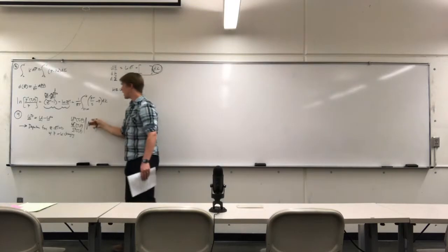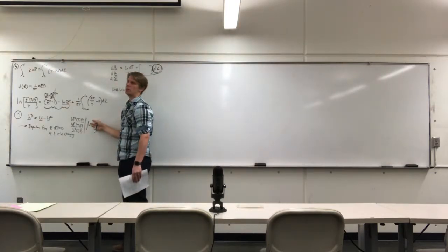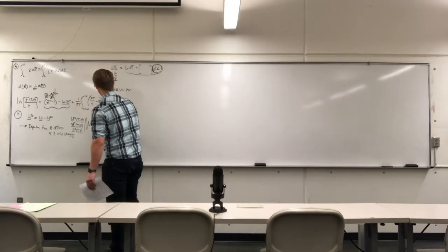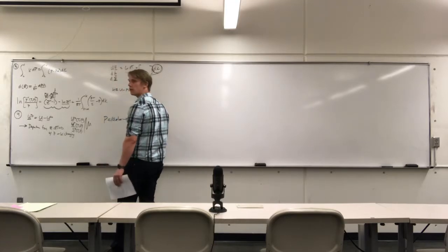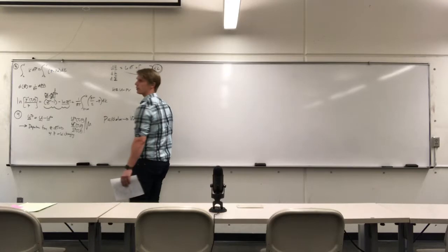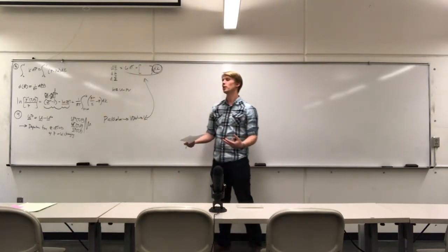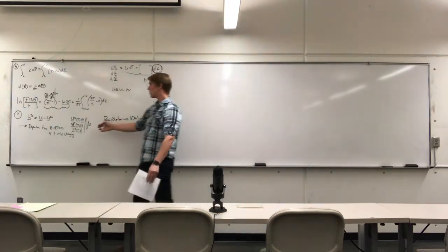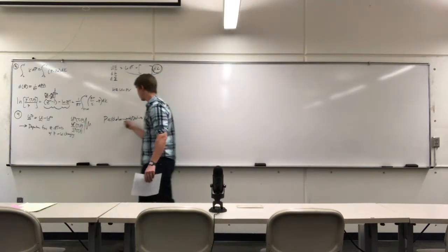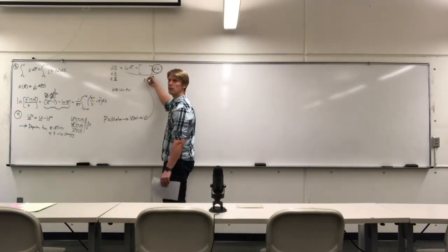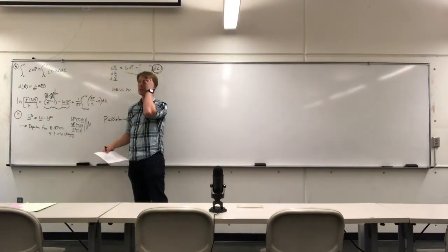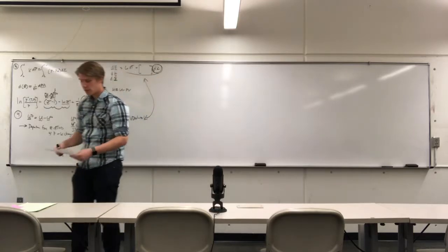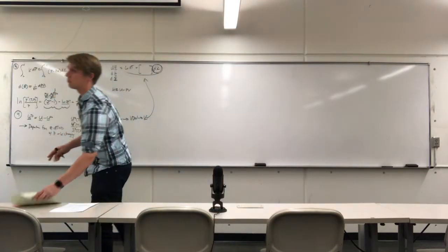So when it comes to actually solving for these here, it's going to be a little bit roundabout. In this case, we say the pressure is equal to 10 atmospheres. But then we need to use the van der Waals equation of state to let us know what the specific volume is, so that we can then substitute it into these expressions here. So when I say as a function of pressure, I didn't really actually mean as a function of pressure. You'll just have to use the pressure through the van der Waals equation to get the specific volume. I don't think it's going to be exceptionally trivial, and it may not even be feasible, to get explicit equations where pressure is the independent variable.